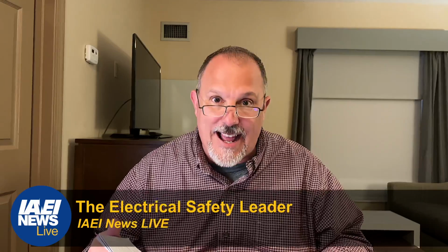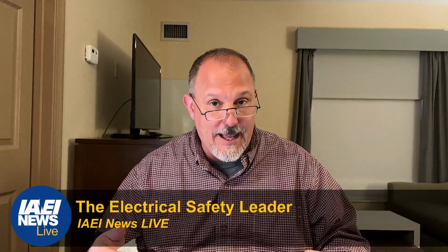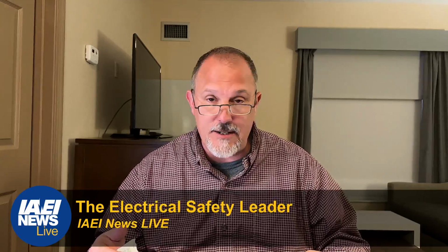The ground fault circuit interrupter is defined as a device intended for the protection of personnel that functions to de-energize a circuit or portion thereof within an established period of time when a ground fault current exceeds the values established for a Class A device. So in 210.8, we added a listed Class A GFCI, and I did not need to do that.